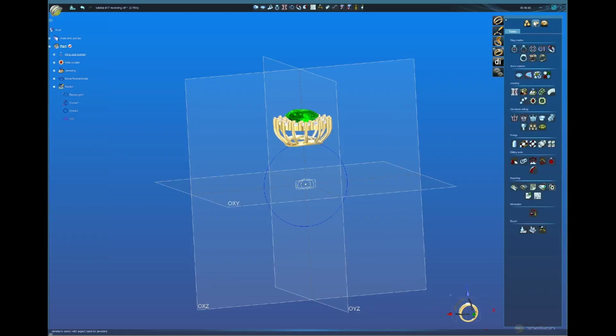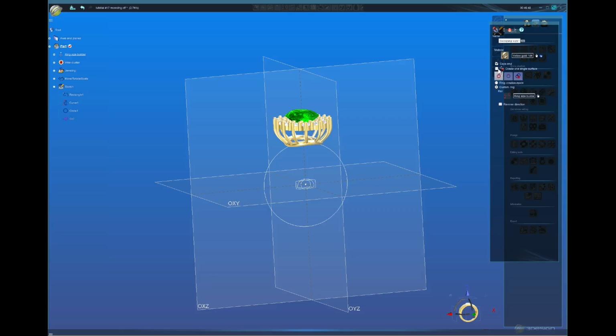We're going to come over here in the second tab and get the sweeping wizard. Click on it. We're going to create a single stone. And oh guys, I forgot one thing here. It's going to be next. Center stone. And over here, we're going to get this profile, and for the inside I'm going to do on click ratio, and I'm going to do width 1.5 by 1.2. It's enough, and you click OK.